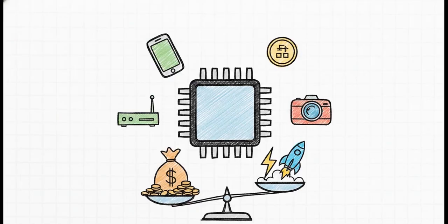So, where do we actually see ASICs out in the wild? Well, mobile processors, network switch chips, image signal processors, and crypto mining chips are perfect examples. Now, what's really interesting about this slide is the development trade-off. Developing an ASIC has a massive non-recurring engineering cost, meaning it is brutally expensive to design and it takes a really long time. But because it's custom built for exactly one job, it offers the absolute highest performance and the lowest power consumption, all crammed into a tiny chip area.